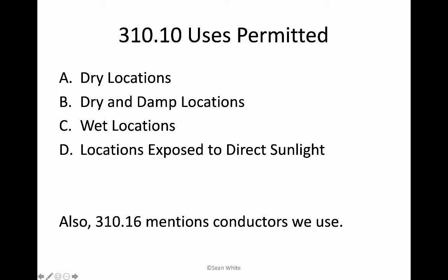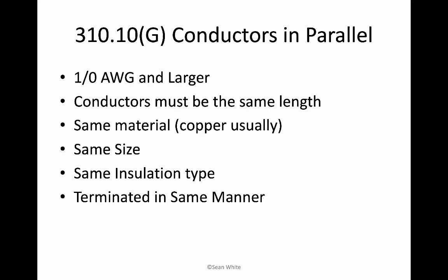If we want to research more and look at the details about all these different types of conductors, such as THWN-2, which is super popular for solar people, if you see a W in the name of the wire, like THWN, that means for water. If you see a -2, that means it can get up to 90 degrees C. Or if you see HH, that could get to be 90 degrees C. If you see a T, that means thermoplastic. If you see a single H, possibly only 75 degrees C. So those are some good indicators of what you're dealing with.